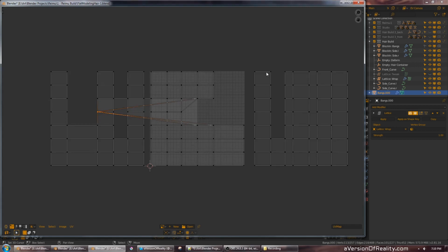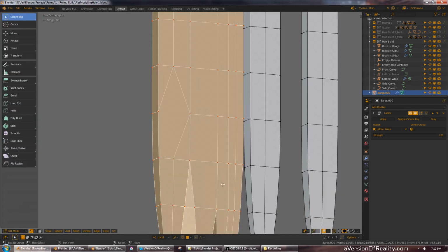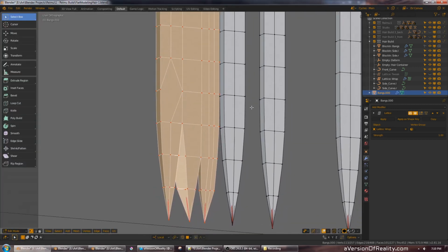The reason I'm keeping it in a clean grid like this is a lot of hair texturing will be done with a texture, either paint or procedural, that's vertical down the hair. So it's nice to have a very clean and even unwrap. And if you put a texture down these UVs right now, then you'll get a tapering to the tip where these points are tapered.